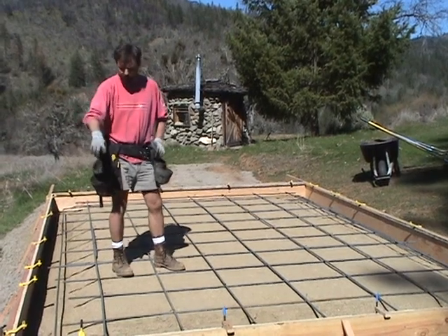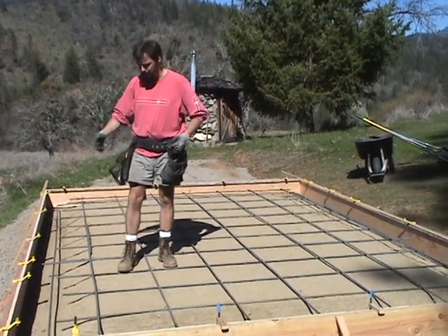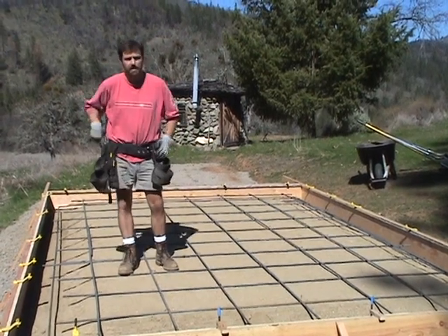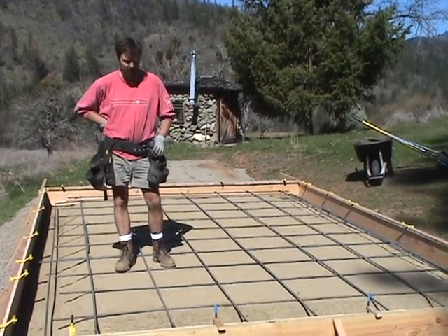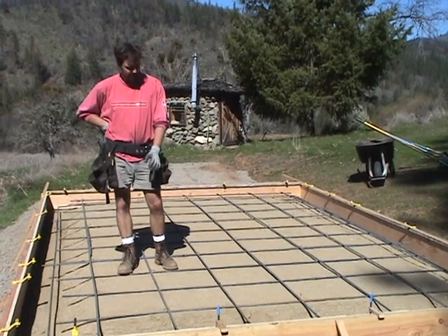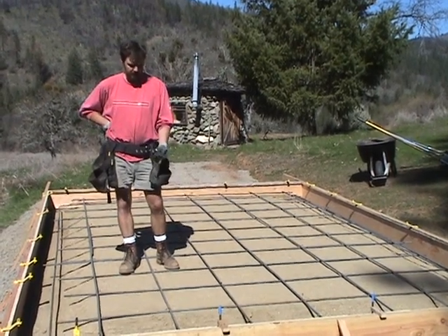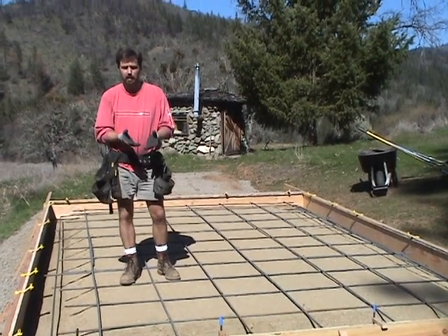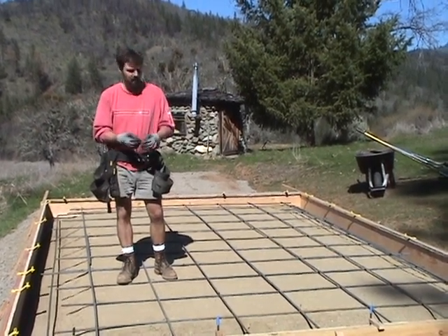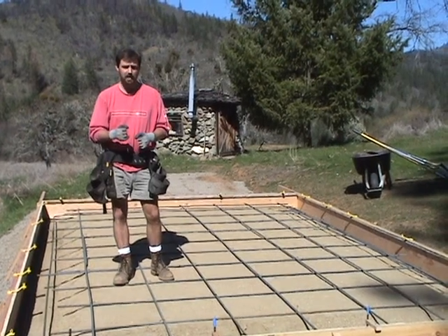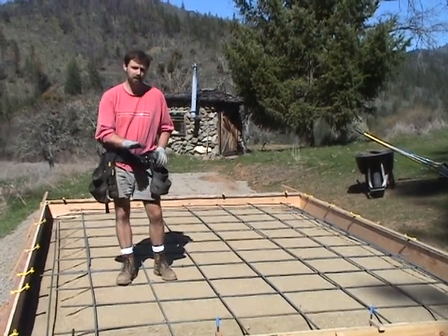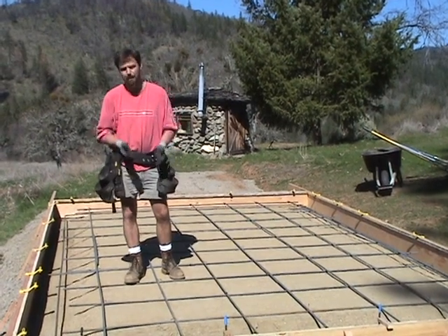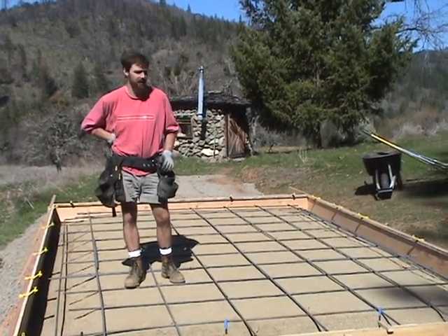I then took one of my bends that runs through the foundation and lifted it up, hanging it from the ends of the grid so that it's elevated and hanging within the concrete. When we pour this, I'll either have to place what are called dobies, which are small little pieces of rock which lift the rebar off of the sand, or I'll have to lift it by hand with a rake as the concrete is poured. The rebar needs to be not below the concrete, but within the concrete. So we want to put it right about in the middle. If we've got a 4-inch slab, about 2 inches off the ground, which is what a dobie would give us.